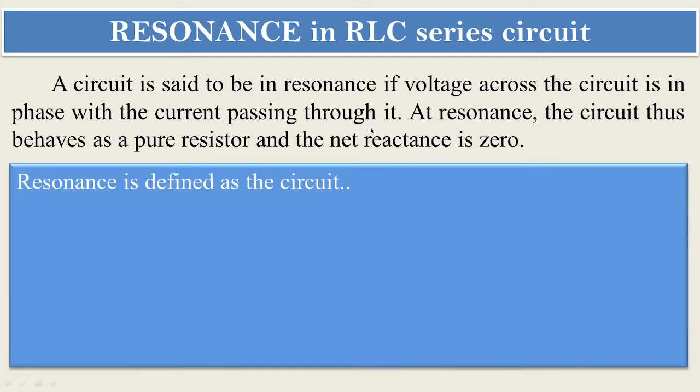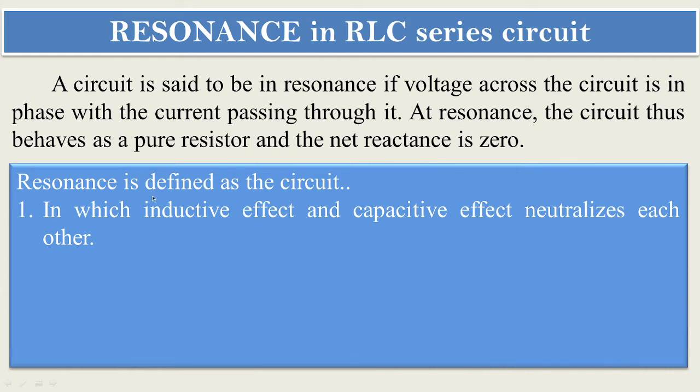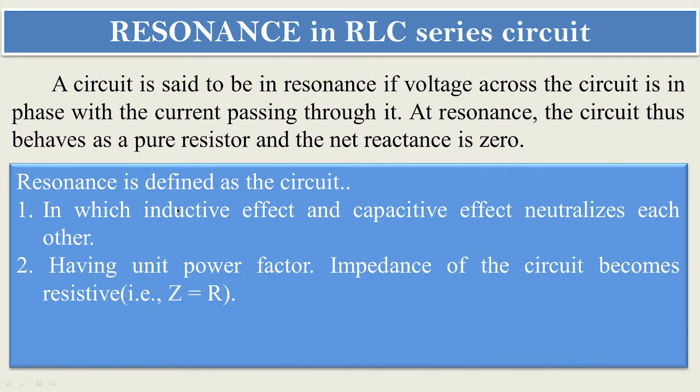Or you can also define resonance as a circuit in which the inductive effect and the capacitive effect neutralize each other. Meaning, it should be free from the reactive component. Or resonance is defined as a circuit having unity power factor. It indicates that the impedance of the circuit becomes purely resistive.